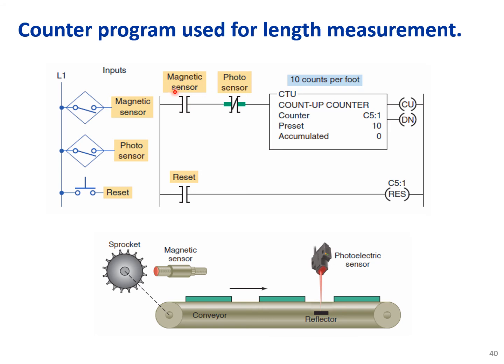So the magnetic sensor is sending pulses, and let's say we have this photosensor. This photoelectric sensor is also false because we don't want to have wood. What is the type of this photoelectric sensor? It is a retroreflective one.